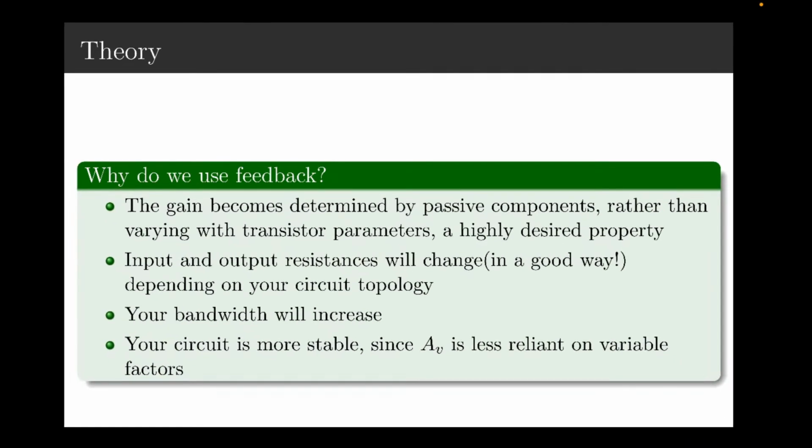Actually, one little thing over here. Why do we use feedback? So, if we have an amplifier that gives a voltage as an output, it becomes a better voltage source. Okay? And I'll give this little example to show you why, with some intuition, not with just the maths. Okay? So, we have RS, the source resistance. We don't know what this resistance is. Let's assume it to be some fixed quantity for now.